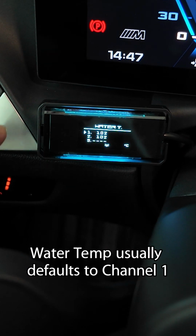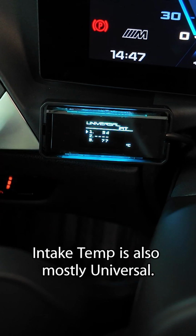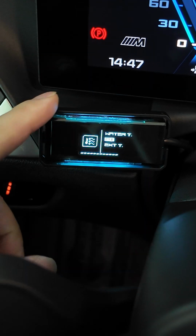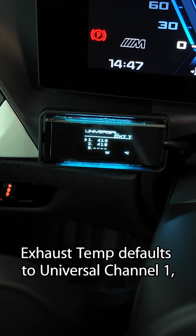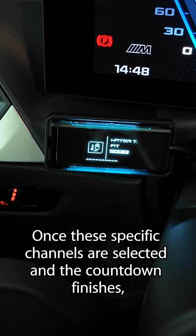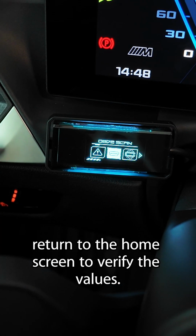Water temp usually defaults to channel 1 and rarely requires adjustment. Intake temp is also mostly universal. Some vehicles may have multiple intake sensors, so just pick one for reference. Exhaust temp defaults to universal channel 1, though Honda vehicles require manual activation due to their specific requirements. Once these specific channels are selected and the countdown finishes, return to the home screen to verify the values.